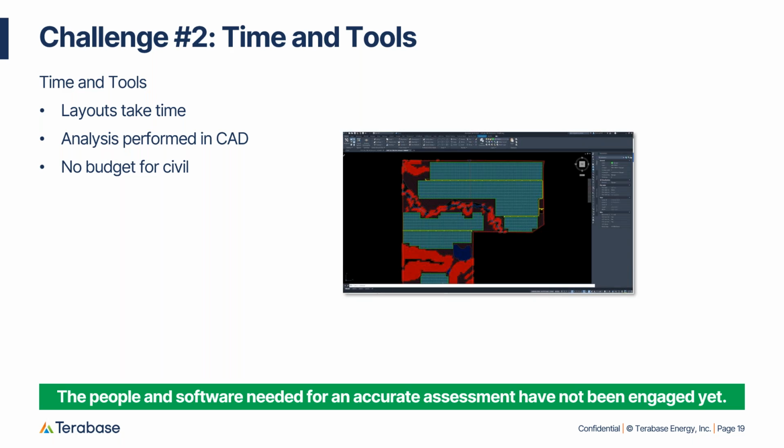Our first challenge would be limited data. We may not have a layout, may not have topo. Our second challenge is time and tools. These kind of go hand in hand, but even if a layout does exist and a topo is available for the site, the second challenge is not having the time or the tools to develop an earthwork assessment. These take significant time, and they also take expertise.